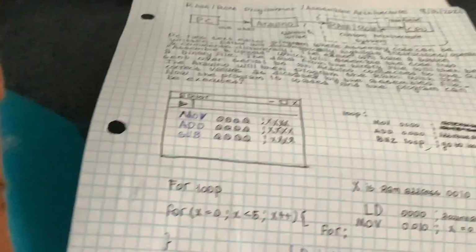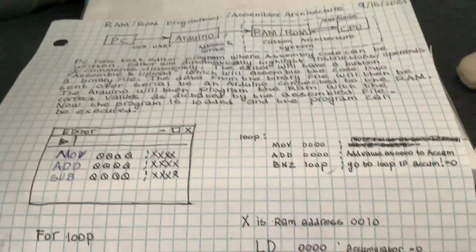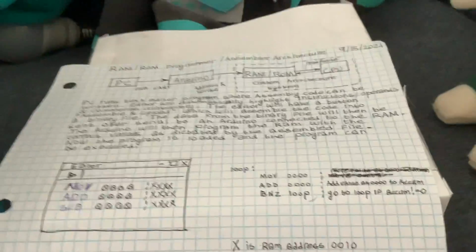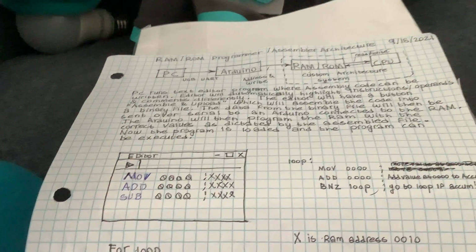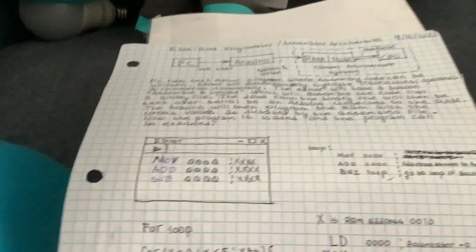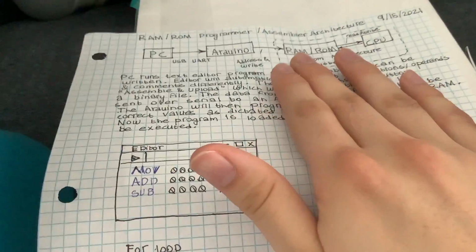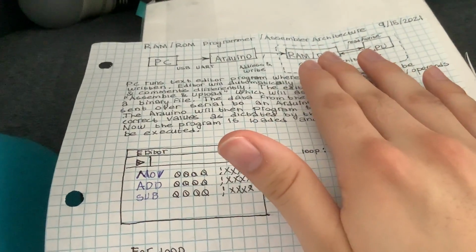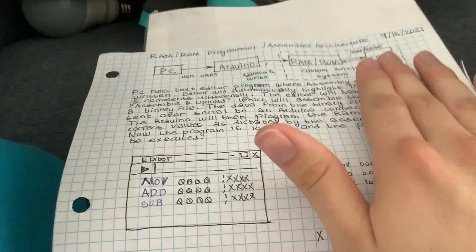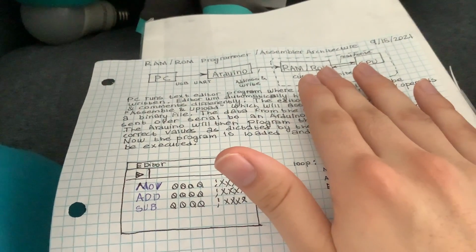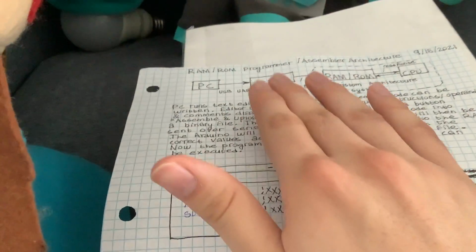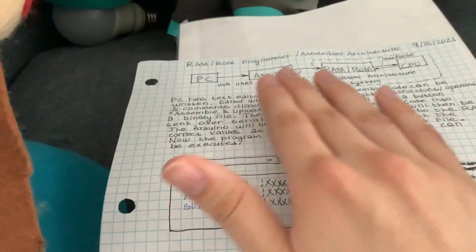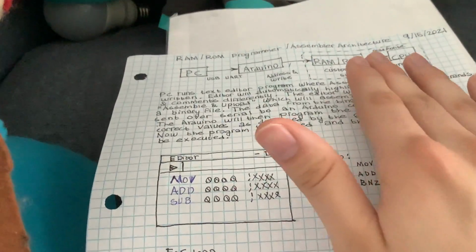And what the Arduino will do is connect to the ROM, which I will probably use RAM chips in place of, just because I don't have any ROMs to use. So how it would work is that the CPU has its own RAM, and then there will be another RAM chip which will act as a ROM chip for the CPU, so the CPU will only be able to read from the ROM chip, but it's really a RAM chip, and the Arduino knows that, and the Arduino can write the program to that RAM chip.